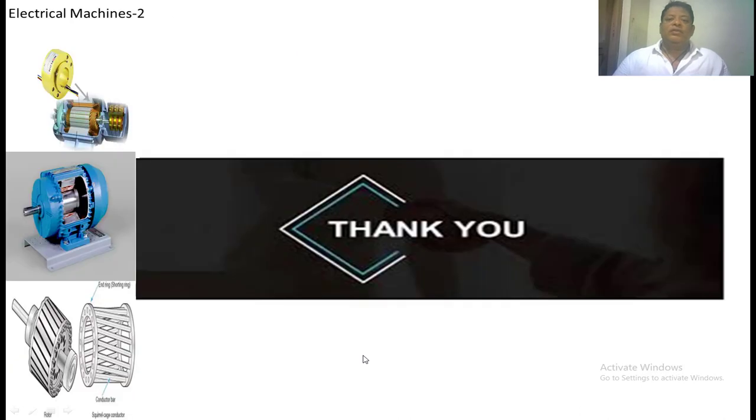In this class, we have discussed why we have to use a single phase induction motor, and the construction of a single phase induction motor. Why the single phase induction motor is not a self-starting induction motor. Next, we have discussed the double field revolving theory. From the double field revolving theory also, we proved that the single phase induction motor is not a self-starting induction motor.